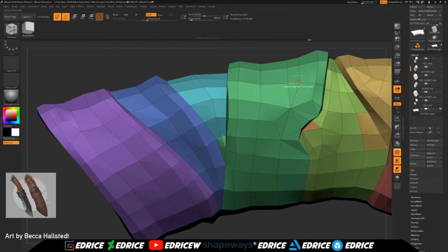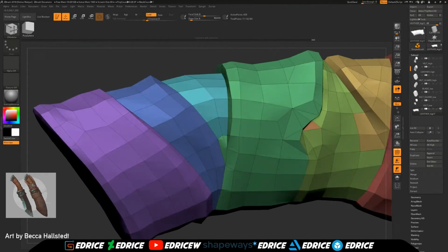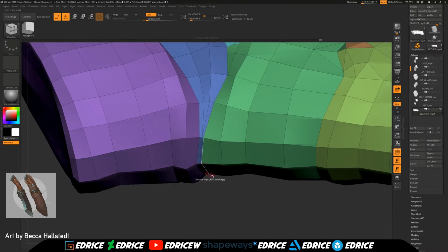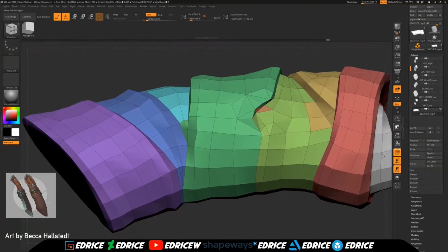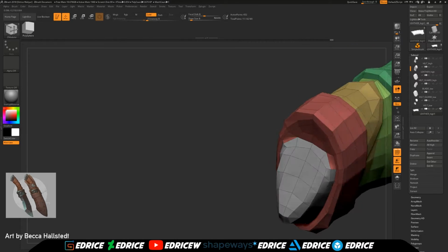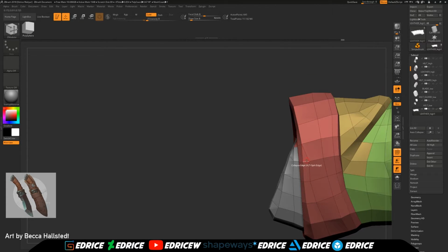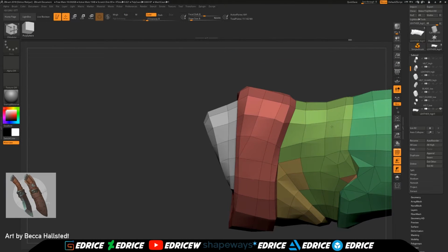Now we can collapse any useless piece of geometry. This is too small of a detail. That edge is too small, so it's not contributing to the overall shape. Here that flow is a bit wonky. Getting rid of that edge. That is not serving any purpose.